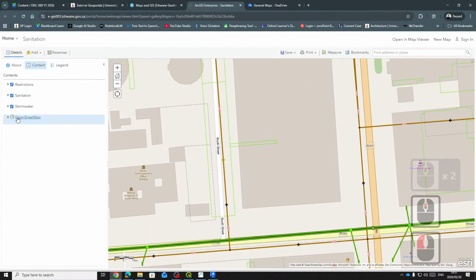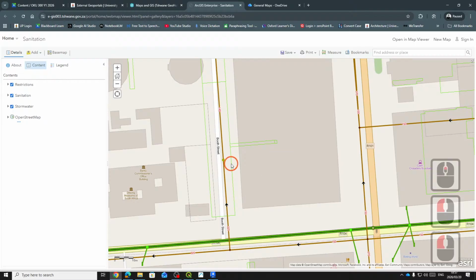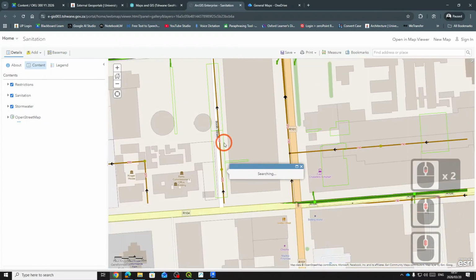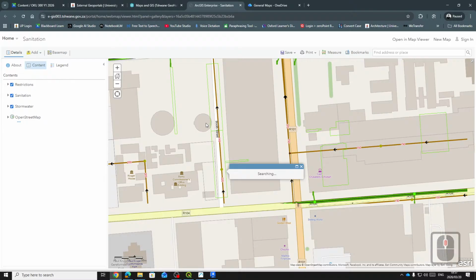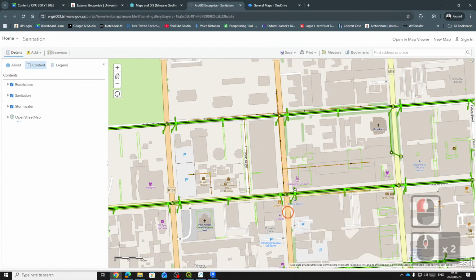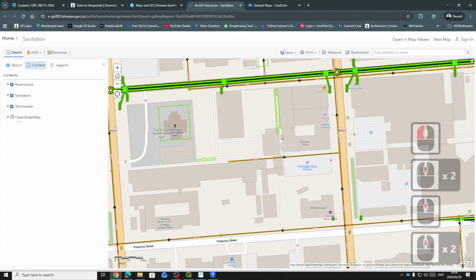Let me just switch off this map for now. Okay, I can't. So this green line is a servitude, and guess what? It coincides with a big stormwater and maybe a road. They had to put that there because there's a big sewer connection there. So that green line is a road reserve. Here's another reserve. See, servitude, type road. So that was reserved for a road in future. So you can't build there. All these restrictions, these reserves on these sites, it'll tell you what it's for.